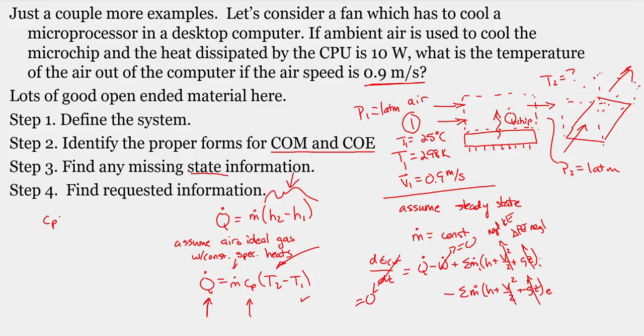And the mass flow rate, we know, is given by this expression here, where we need the density of air. So the specific heat's pretty easy. You're going to Google specific heat, air, standard temperature and pressure, and you're going to get a number. You'll find it in a million different places. The density of air is typically not tabulated.